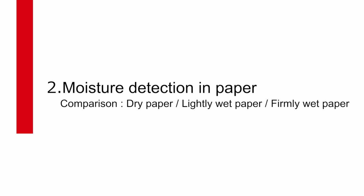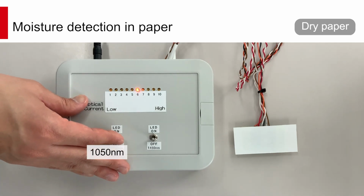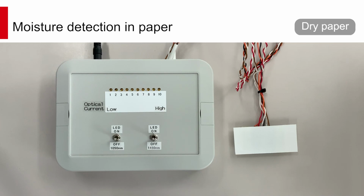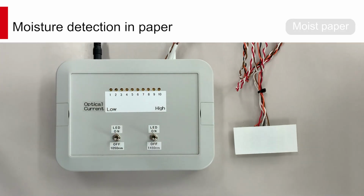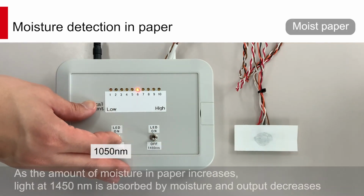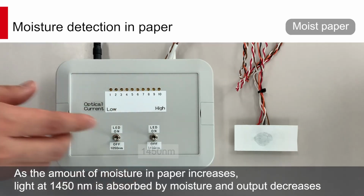Next, let's compare dry and wet paper. On dry paper, neither value changes, but since light at 1450 nanometers is absorbed by water, the more moisture the paper contains, the lower the output.